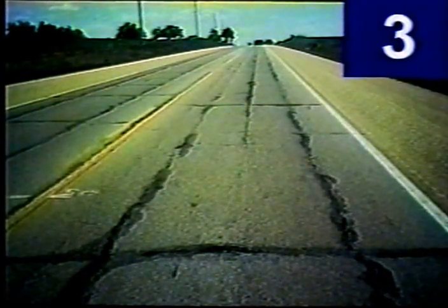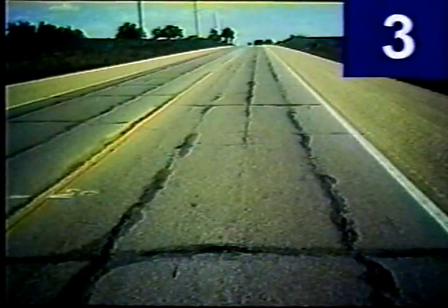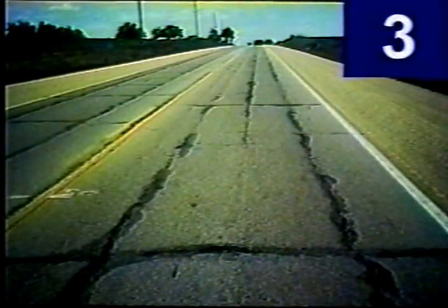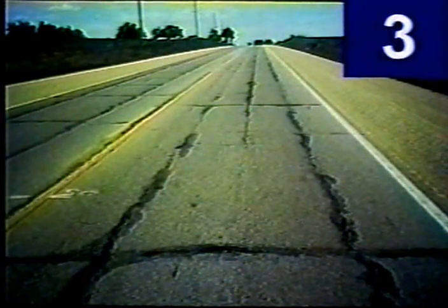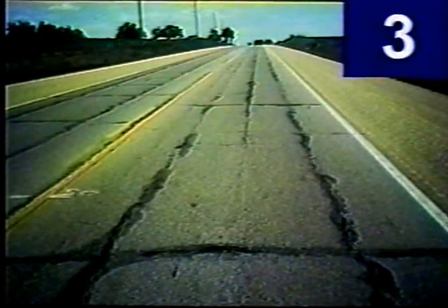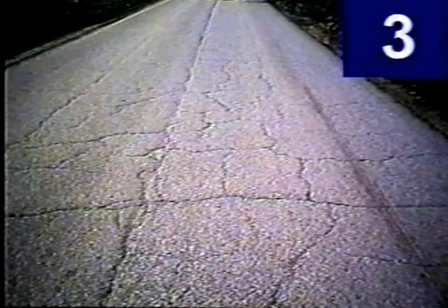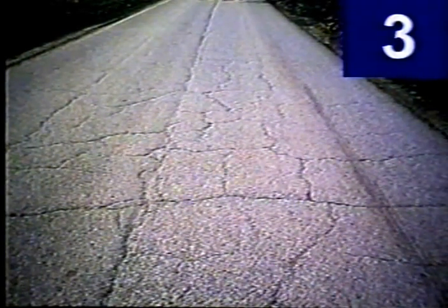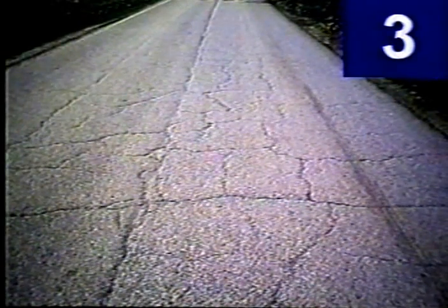When you see cracking to this extent, there is going to be a problem, in my view, of just simply overlaying this. This would be a great candidate for a milling operation. If you could mill off this crack pattern and then put an overlay on, you'd have a much better performance of the asphalt overlay. You now have more extensive block cracking. The cracks are wider here, and a more structural overlay would really be appropriate.